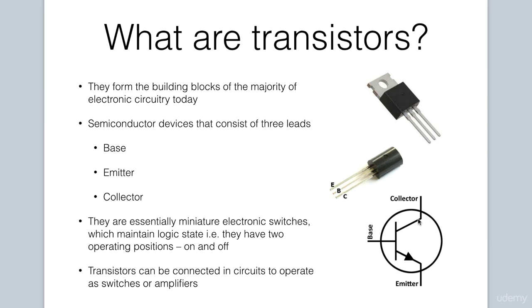Transistors can be thought of as miniature switches and primarily operate in 2 logic states, on and off. Transistors usually have 2 main modes of operation. They can be used as switches to quickly switch a circuit on and off via an electrical signal. This can be controlled very accurately, up to thousands of times a second. And they can also be used to amplify signals in a circuit. In our circuit, we are primarily using the transistor as a switch to turn our motor on and off.